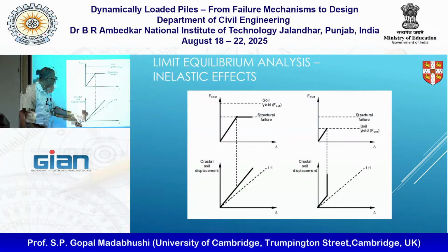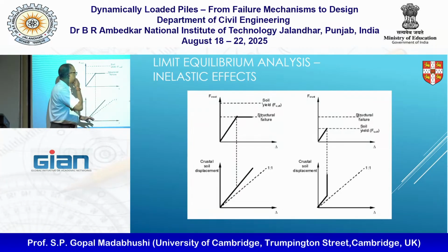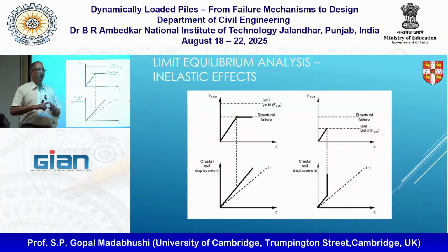By looking at how much elastic deflection I get for the pile compared to how much crust displacement I can estimate using something like Newmark sliding block. If this is the case, we are designing for the pile to fail way before the soil will fail, right?